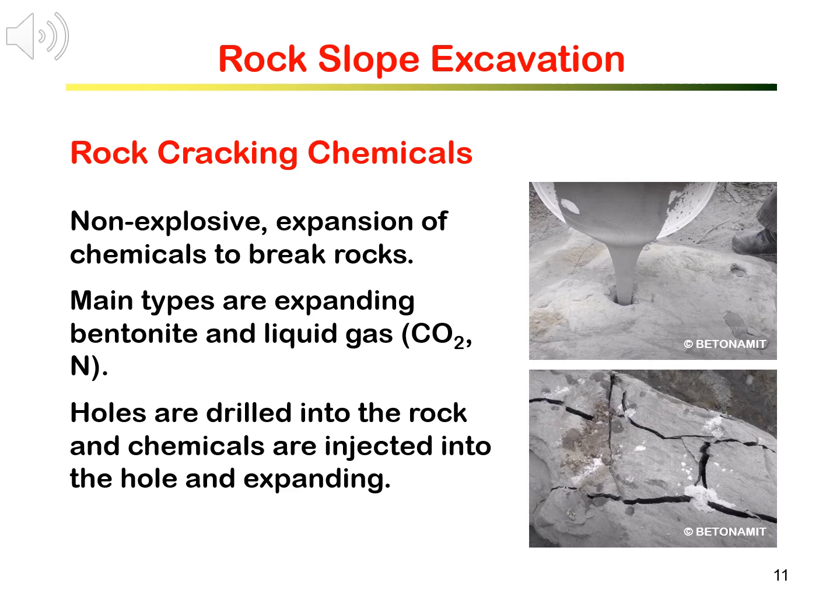Chemical bentonites, for example, bentonite shown on the right, are commonly available. They are in a bentonite mix and are poured into the hole to fill the hole. When the bentonite solidifies, its volume increases and forces the rock to crack in the hole. You may have anticipated that the process is slow and the cracking can take a few days. That is perhaps the main disadvantage.